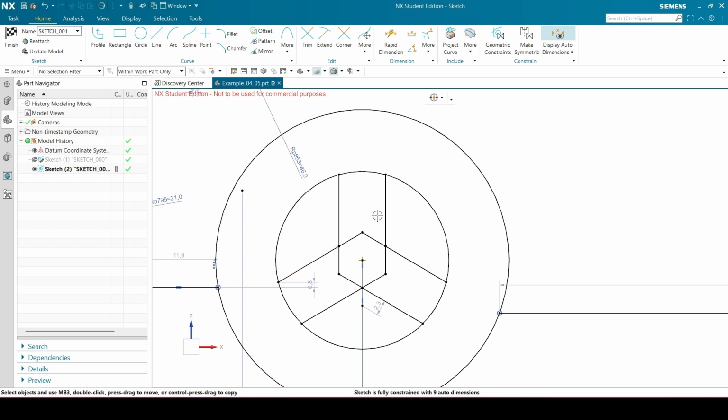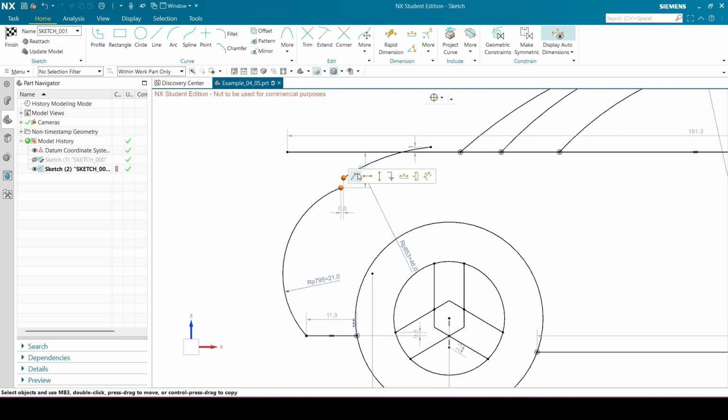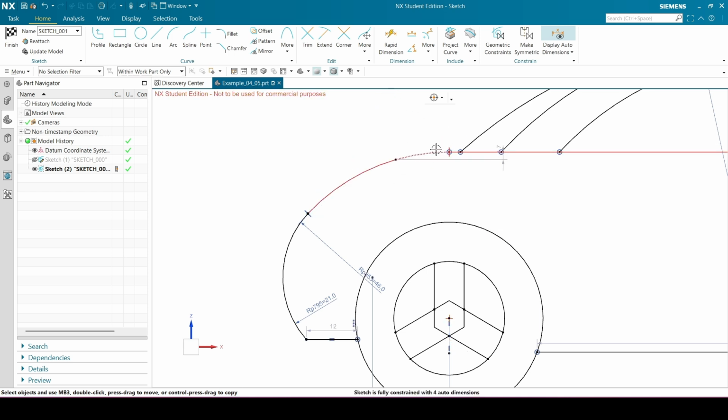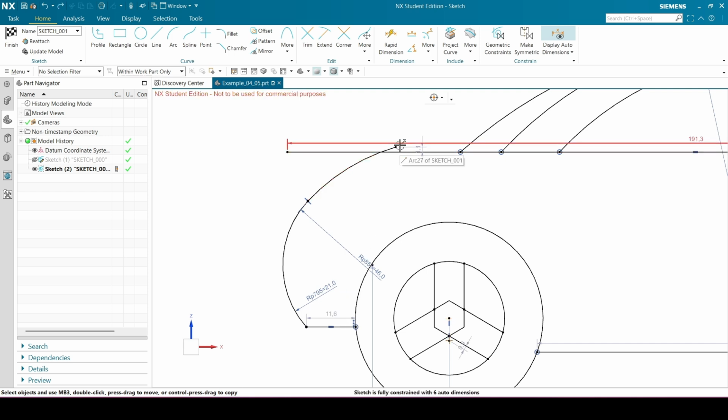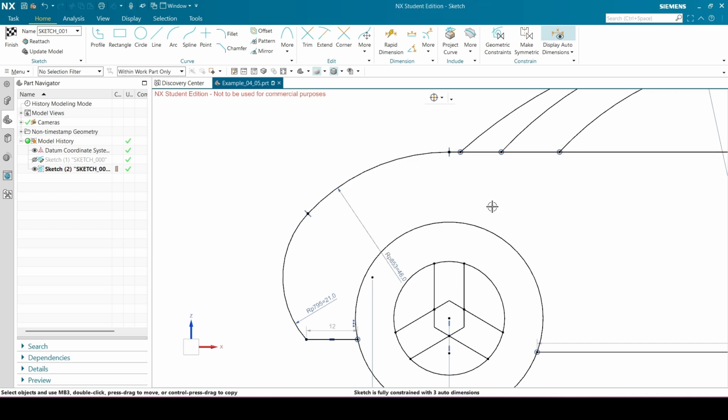Okay, and I just marked off the dimensions that I put in. Then I'm going to make these 2 points 1 point, and then these 2 arcs should be tangent. Then I also didn't do exactly what I wanted it to do. I want to make these 2 points also 1 point, and they should also be tangent. Okay.